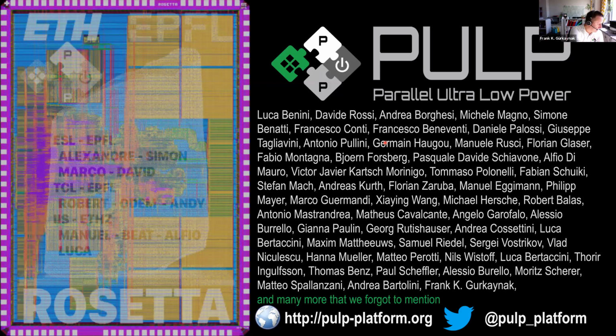Let me see if, so there is one who's asking, how did you measure power spent in each unit of the core? This is a great question. There are tricks. So we have a number of our chips, which we will talk about tomorrow in the second part, which have actually separate power supplies. But we also, once we manufacture a chip, measure its power, we also can run analysis tools on the same